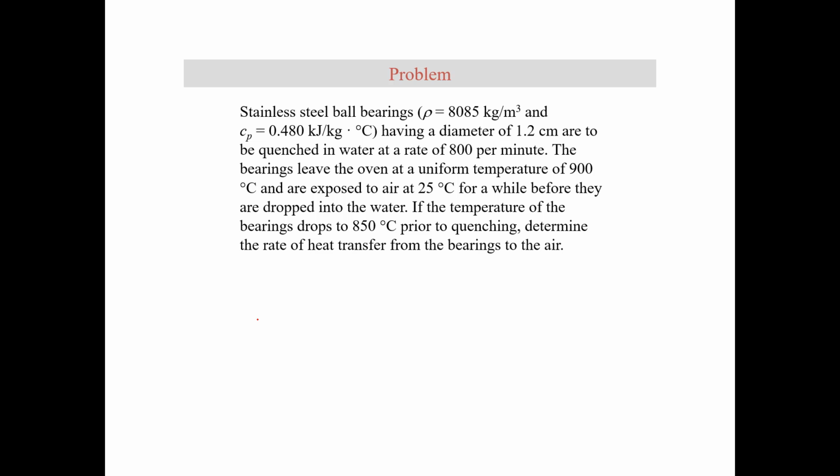In this problem, we have stainless steel ball bearings, each with a diameter of 1.2 centimeters, that are to be quenched in water at a rate of 800 bearings per minute. The bearings leave the oven at a uniform temperature of 900 degrees Celsius and are exposed to the air, which is at 25 degrees Celsius. So they are exposed to the air for a while, and then they drop into the water when they are at 850 degrees Celsius. It's asking you to determine the rate of heat transfer from the bearings to the air.